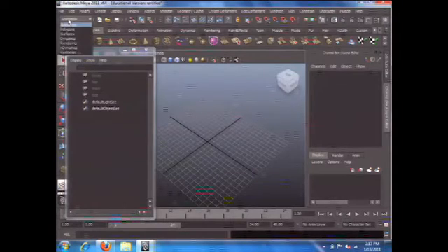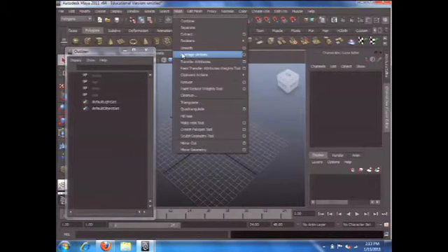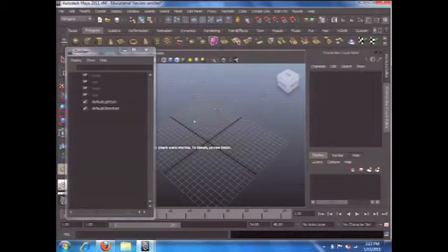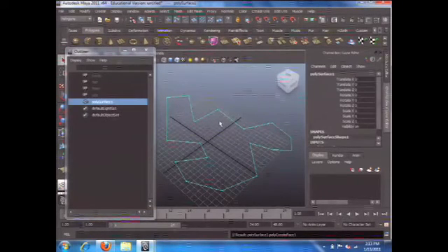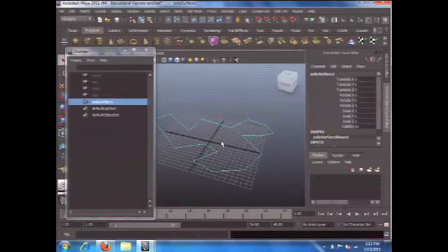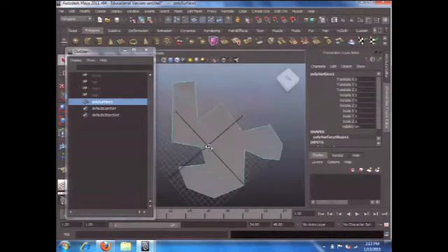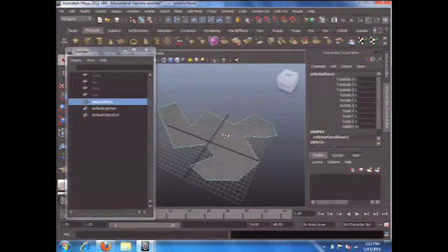So number one, I want to switch back to polygons. In the polygon, I want to create a really rough building footprint. So create polygon tool here. And then I can do a kind of random shape. Enter to finish. All right, so that's what the shape looks like. Number 5, I can turn on the shading. So that is the profile of my skyscraper.